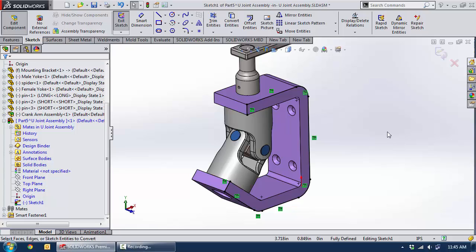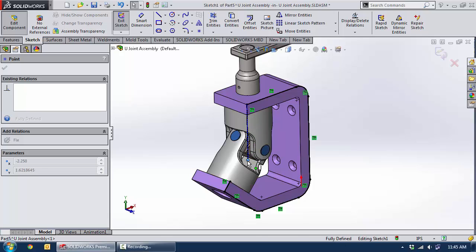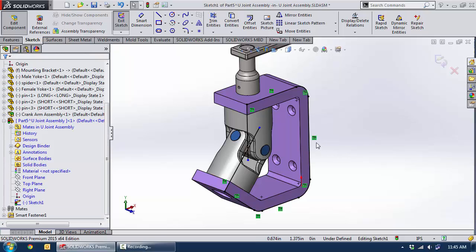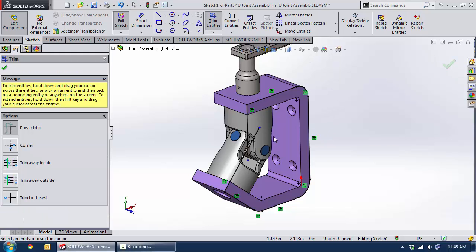And then I'll use a nifty little trick that we have available to us with sketch geometry created from Convert Entities or Offset Entities. And that is, we can drag the endpoints of open sketch segments that are created through that process. Notice also that our sketch has a number of sketch relations on them. The entities have this On Edge relation which references back to the edges of the bracket. Now all I need to do is simply trim away the extra geometry that I don't need,